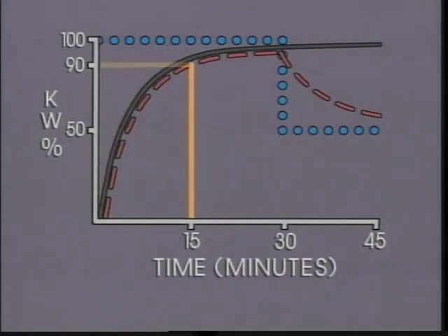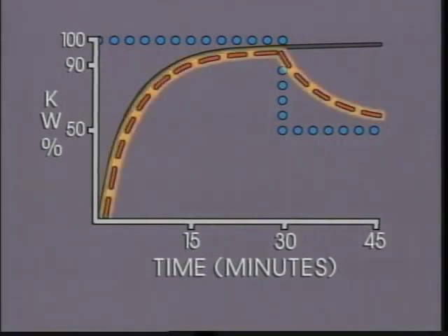And in 15 minutes, the thermal response is only 90% of the load. Notice that the thermal response doesn't near 100% of the load for quite some time after the 15-minute interval. This is where the term lagged comes from when referring to the response method of thermal registers. It's also important to note that demand registration for a thermal meter is continuous. Notice by the dashed line indicating the movement of the pusher arm that the pusher arm does not reset at the end of regular time intervals.